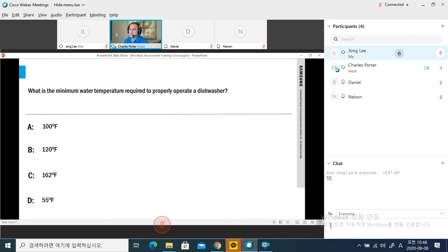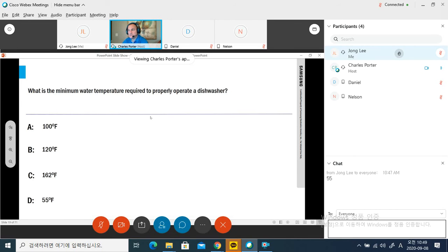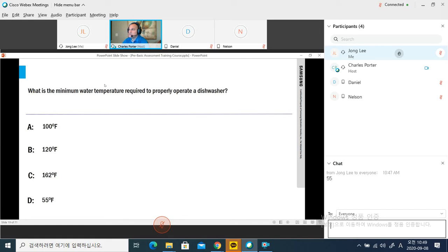That's not going to be the answer. It could be part of it, and you could certainly recommend that to the customer, but there's going to be other things going on inside that unit. If it is a temperature issue and it is the only reason it's not cleaning well, then you're probably looking at something going on with the thermistor or the heater because it's not heating that water properly inside there.